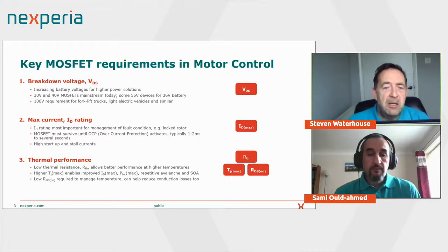Now, as that current flows, and it may be an overload current, when we try to turn the MOSFET off, there are obviously going to be some voltages generated over the inductances and resistances within the circuit, and it may not be possible to actually turn the device off as completely as you'd want. So as you switch on a MOSFET, for the logic level you want the voltage to be above 1.5, 1.7 volts.